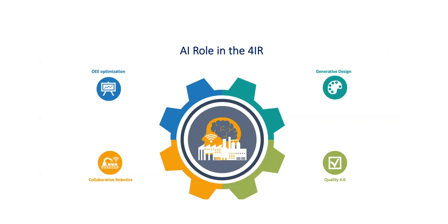Let me explain a very clear example. When you're working with classical recipes in drug manufacturing, for example, in tableting, the recipe says: put raw material A, so many kilograms, in the granulator. Put in this ingredient, the colorant, and so on, and mix the mixture for 7 hours. And this is the recipe that you have to follow step by step. You cannot modify the recipe because the recipe has been submitted to the health authorities.